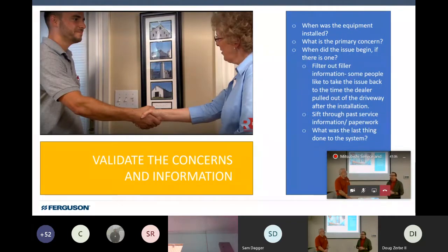Okay, now all of a sudden I'm thinking that may change the whole direction I go, because now I may be looking for a refrigerant issue if somebody put a pound in, or that past tech didn't understand what he was dealing with, inverters and variable frequency refrigerant flow. So all of that to say, when we're going out for service, it's really good to have a good overview of the system, understand what's been done recently to it, if anything, and why you're out there. Right.